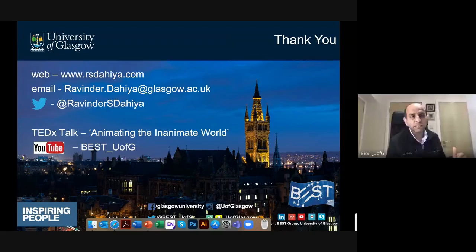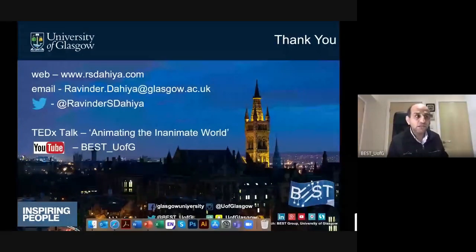You can have a capacitive sensor as an example. When you press the capacitive sensor, the distance between two electrodes would change because the dielectric between them is a soft material, and that leads to a change in the capacitance. You detect the change in the capacitance, convert that value into a digital value, and then you can further process it.